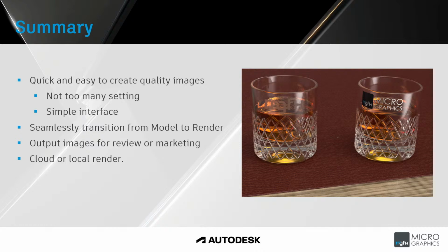So if you are looking at having little LED lights or screens within your design, for the color itself that you apply, that appearance, you can actually say it's emissive, it's giving off light. So you can get a glow of light around that component. So it's a quick, simple, easy interface to be able to create quality renders.